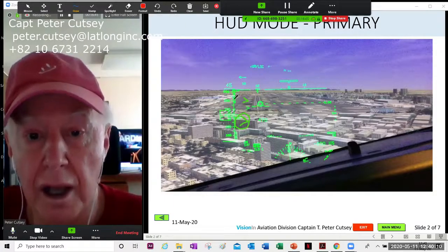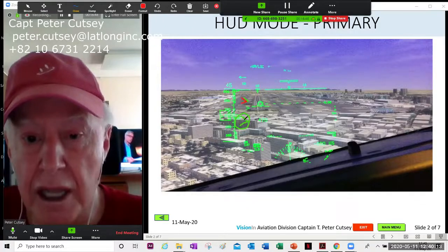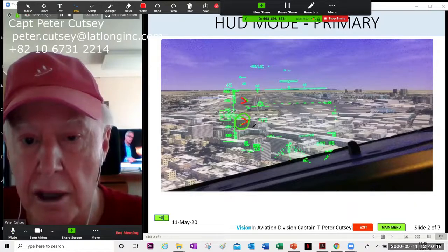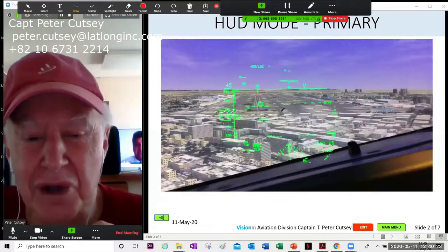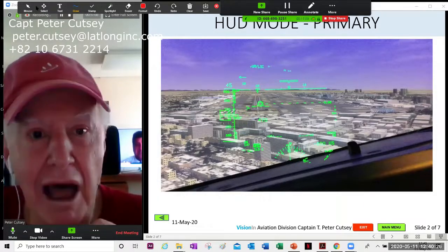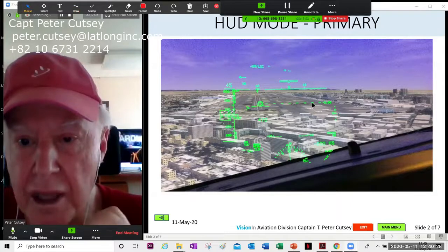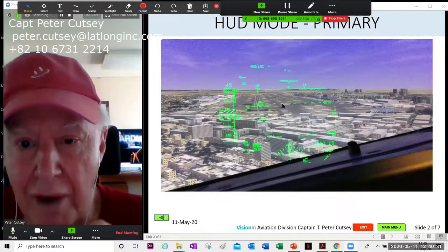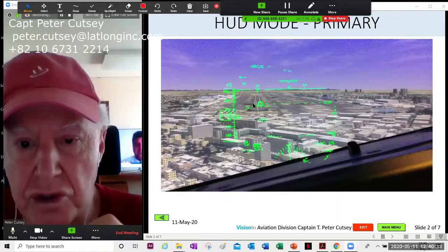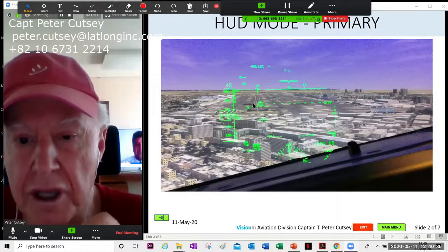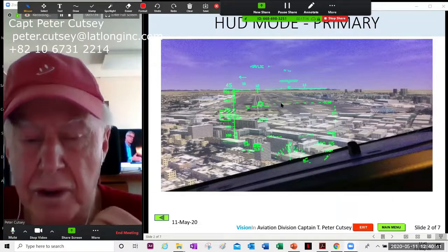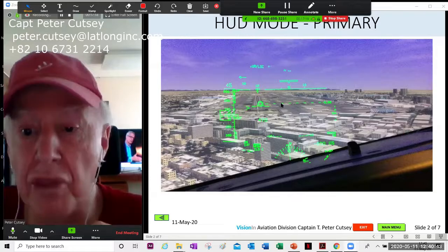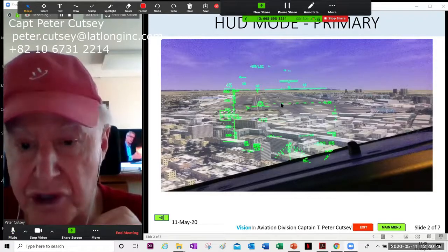So above the wingtip, accelerating, and below the wingtip, decelerating. Too bad it wasn't that way in color of the airplane, but it's all one color. Okay, so the line that you see here is the 3-degree reference dashed line that you've entered into the MCDU before you did the approach that actually mirrors the glide path once you're on the glide path, once you're on the ILS itself.